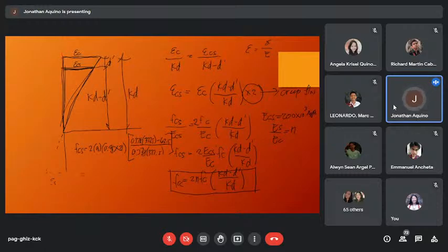So FCS is 0.378 times 337.5 minus 62.5 divided by 0.378 times 337.5 times 0.45 times 21 times 2 times 9. So FCS is 86.77